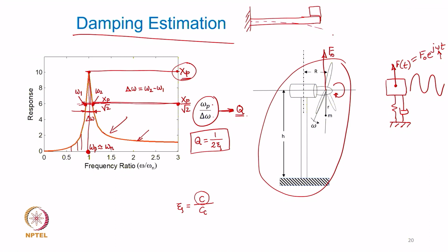Once I displace and release it, it means that I am giving some initial excitation to the system. Then there would be a time displacement plot that I will get. Okay. This is the amplitude and this is time. This graph, you remember, we have discussed for an underdamped case, the amplitude logarithmically decreases, and we defined a parameter called logarithmic decrement. It was shown to be 2 pi zeta over square root of 1 minus zeta square. You remember that?